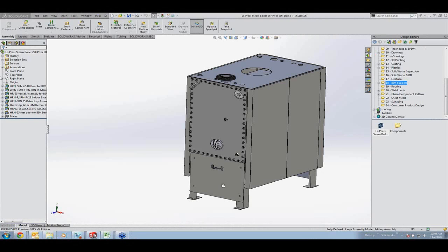Now we can choose the curve degree that we want here. So third degree, second degree, etc. Here I'm going to choose fifth degree. I can go ahead and move these around if I want, or put them back in the approximate location they were before. It's a really nice tool there to be able to convert to style spline.